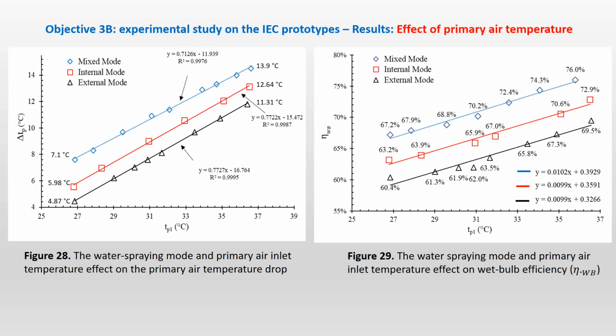The internal sprayer has simply modified the performance of the system, and having the mixed mode can cool down the air by 14 centigrade if I send it at a temperature of 36.8 degrees, performing better when the temperature is higher, simply once again because the delta T across the plate is going to be higher, with the constant secondary air temperature.